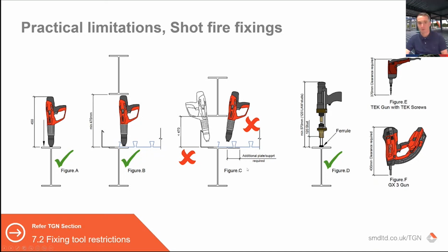because if you've designed a bottom beam in a step like this to be composite, that it needs shear studs, and you can't get the gun in, you can't weld the shear studs, so you then have to find a way on site of welding those studs, not using the traditional through deck welded shear stud approach. So they would need to be welded by the fabricator, which means mobilizing different works that potentially weren't planned, etc. So in that scenario, you're probably better off designing the lower beam as non-composite to avoid it.